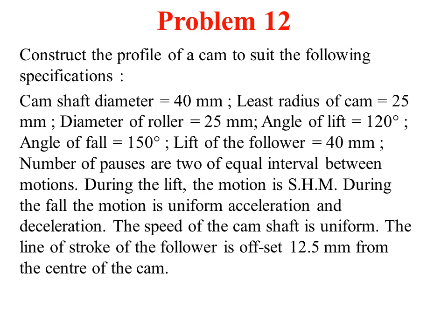We should know how we define a base circle. We have defined in earlier sessions base circle as the smallest circle that can be drawn to the cam profile. So here they clearly mention least radius. So least radius of the cam means it is the base circle, not camshaft diameter. So here the base circle will be least radius of cam, that equals 25 mm.